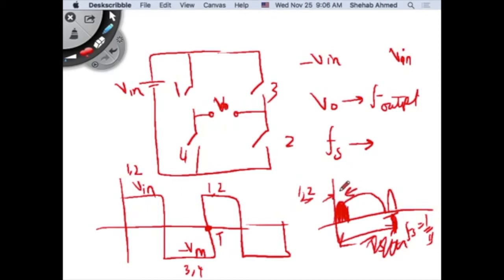You're confusing duty cycle now with the period. Your duty cycle is the time on over the time on plus time off. Or this is now the full period. You're confusing both now together. So I'm not asking for the duty ratio, I'm asking for a period, right? Or the inverse of that is the switching frequency. So how fast am I switching devices 1 and 2? I'm switching them one time during this period. So their switching frequency is 1 over this period, right?